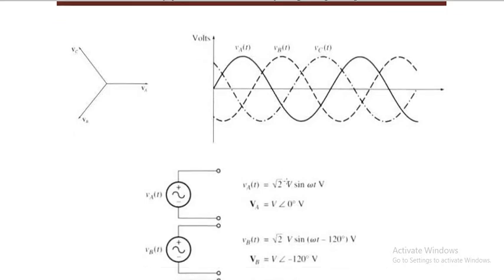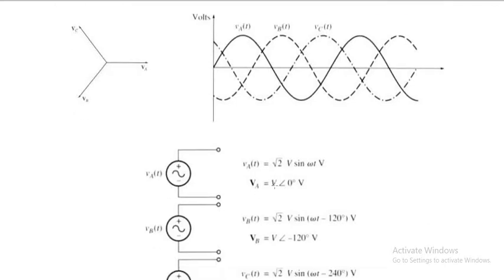Okay, so to find out the value, the RMS value is V, so this maximum value is root 2 V. Okay, because how do we write voltage equations, current equations? Remember, V is equal to Vm sine omega t. So here the value we need is the maximum value. If the RMS value is V, the maximum value will be root 2 times V, isn't it? Yes.